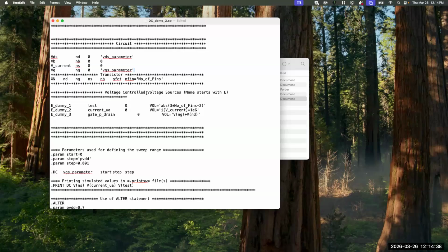There are many hierarchies in SPICE code. Remember, there is a parameter that you're passing here. There is another parameter that is set in a Verilog code. What you haven't seen yet is sub-circuits. So oftentimes when you have small scale circuits like this, we create a sub-circuit of them, and we use that sub-circuit in a bigger circuit, and we use that sub-circuit in another much bigger circuit. So gradually there is a hierarchy of parameters.